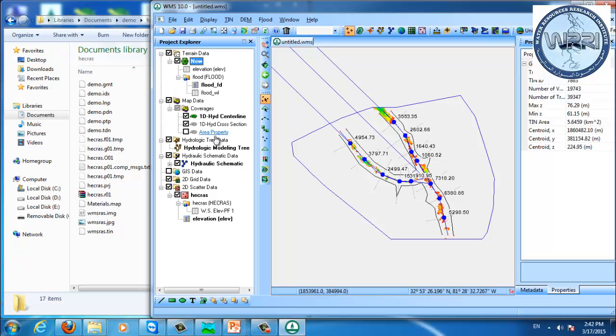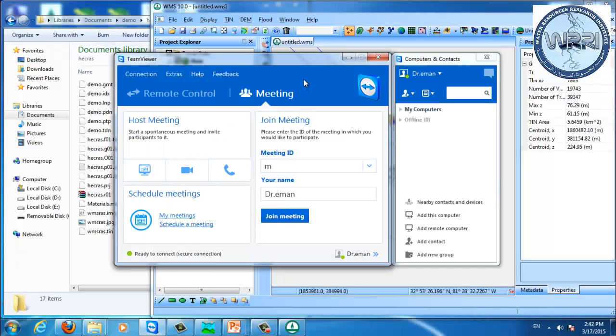Do you think if I use 2D, it will solve this problem? If you use 2D HEC-RAS, maybe not, because it's just a matter of delineating the floodplain. So the main parameter which will affect the result is this radius distance. So just change your radius.